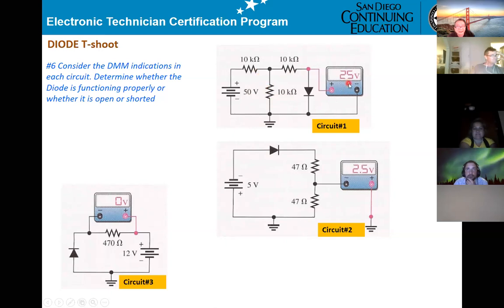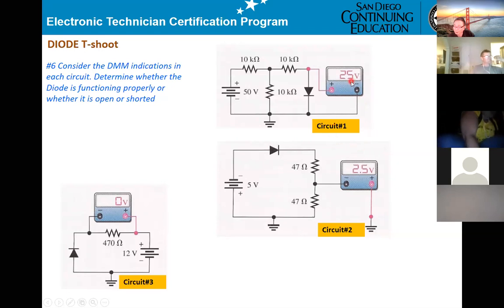25, yeah. Okay? So if you interview with me, I will be asking you: I measure at this point, I get 25 volts. Tell me, diode open or short? Then you say open. That's correct. However, I will be asking you, how come you get 25 volts?